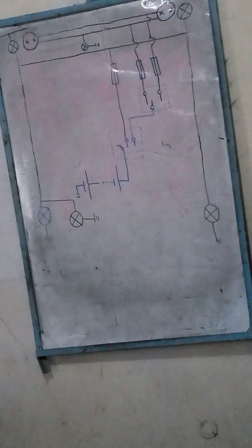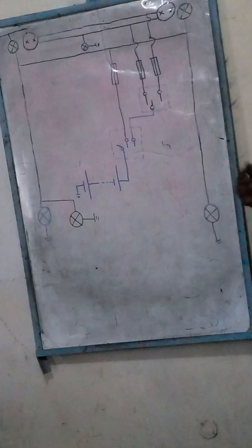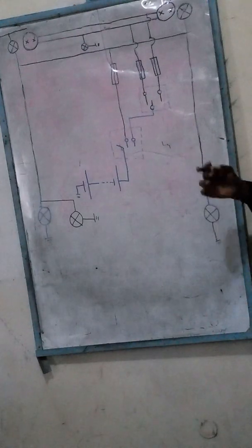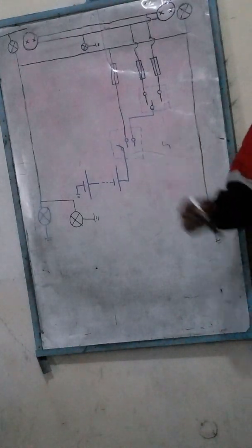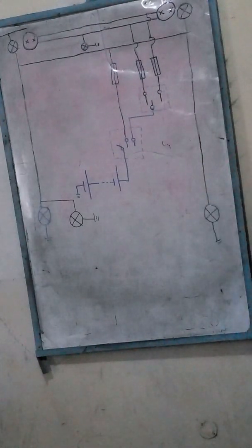At night, we need additional light in order for us to see the road ahead. It is also a legal obligation that any vehicle which is used on public roads should be equipped with a standard set of headlights that have a dip facility. That is, we should have a facility whereby we can reduce the brilliance of the lamps in order to prevent dazzling the other driver coming from the opposite direction.